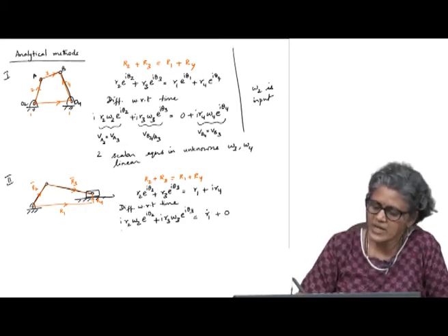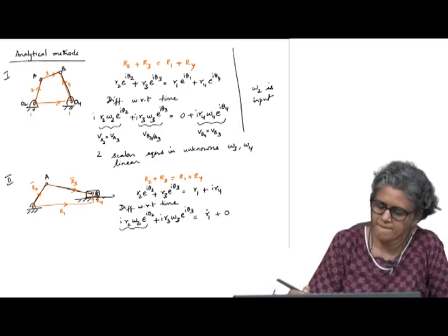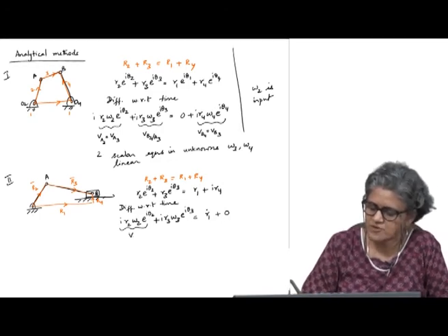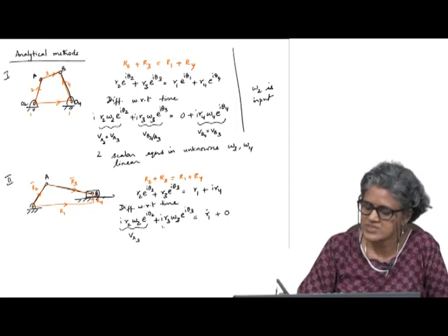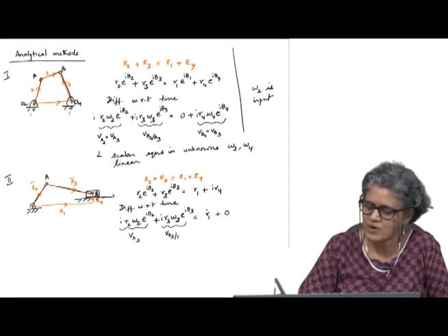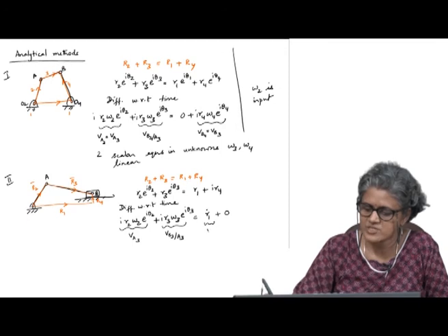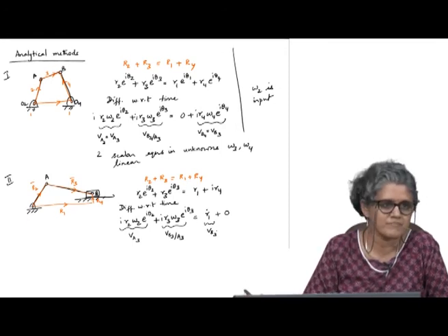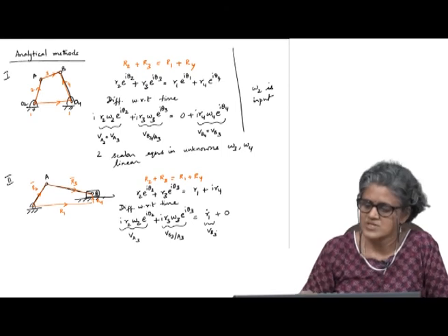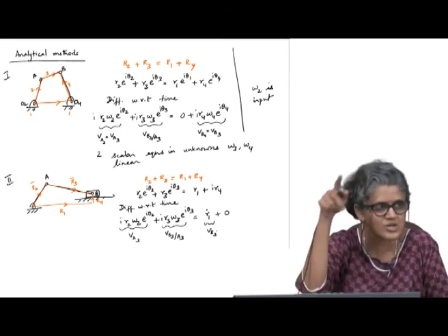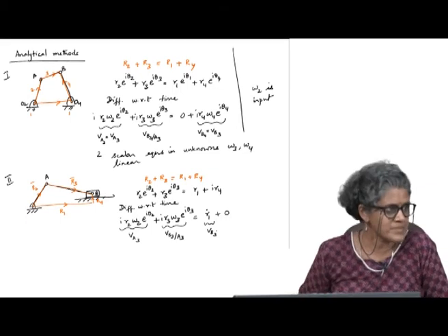Okay. So, now when you look at this, is the velocity of, what is this, the velocity of A on body 3 or 2. This is the velocity of B on body 3 relative to A on body 3, and this is the velocity of B on body 3, absolute velocity of B on body 3, because it moves along the slider path. So, this is again the same equation that we used to construct your velocity polygon. Okay, so, that follows from this.